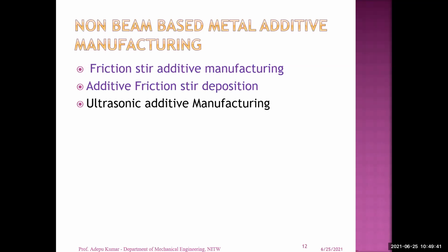What is the importance of recrystallization temperature? Once you have heated the material to its recrystallization temperature, the grain boundaries are weakened. The strength of the material is a function of bonding between the two grains. So you are applying heat to destroy the bond between the two grains. That means the force of attraction between the grains reduces by increasing the temperature. Then you can apply force, and according to the force direction, the material is going to deform.